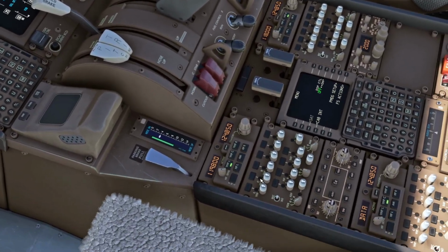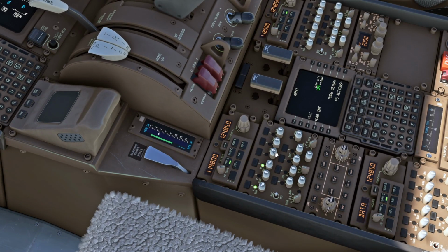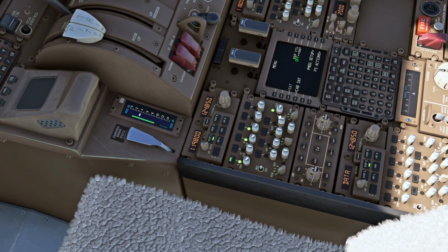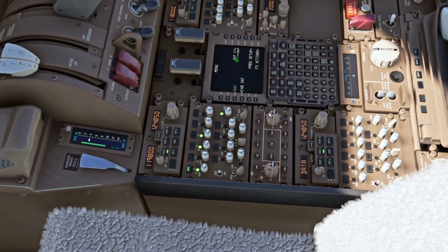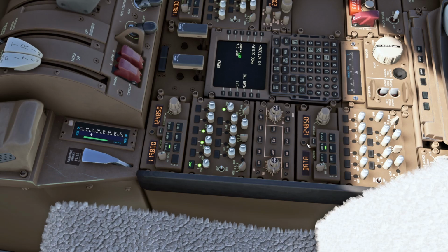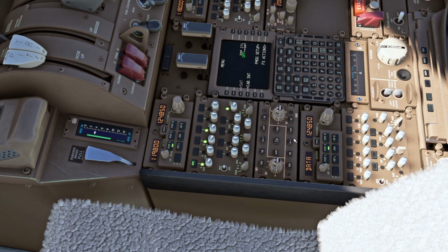It's also good practice, once you get into the seat, to turn on some of the radios, especially if you're on VATSIM. You want to make sure you select a proper microphone, and in real life the flight interphone would be nice to have on the speaker to make sure that we can hear the ground crew when they call us. And this radio is configured for data, which helps with uploading the flight plan through ACARS in a moment.